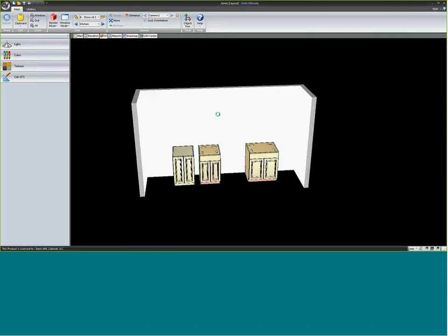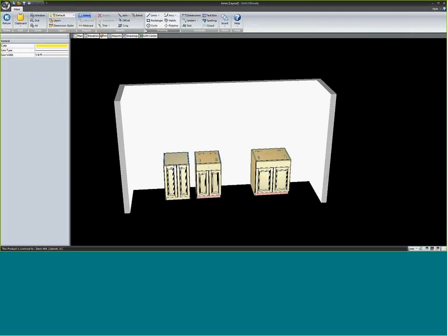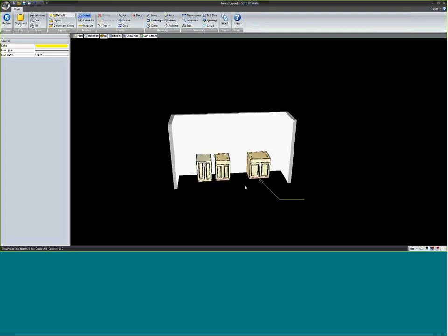The nice thing about this camera lock, which is a new feature in version 8 that we've never had access to, is, and we haven't talked about CAD at all, we'll cover that tomorrow, but just to give you a quick teaser, when I have a locked camera view, I can access CAD mode now. Before I could only access CAD mode in plan or elevation. Now I can come in here and put leaders on CADs in 3D and text out here in 3D and stuff.